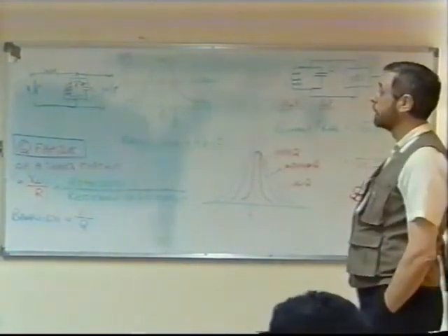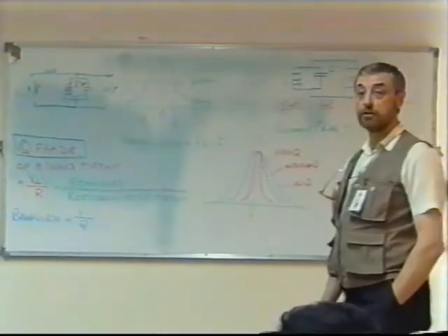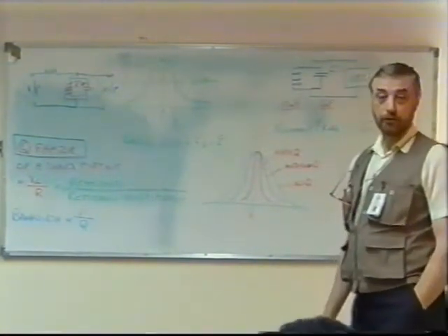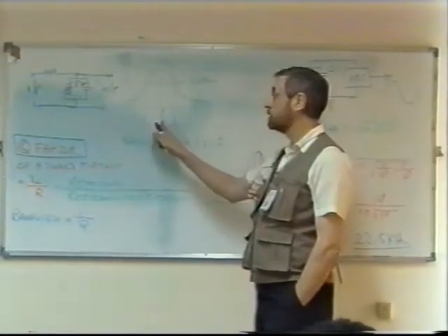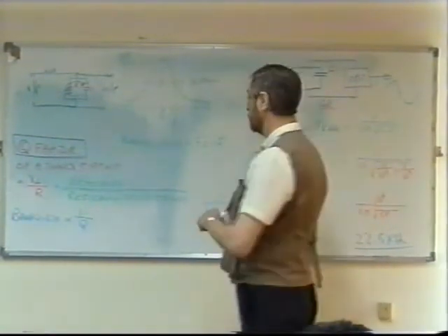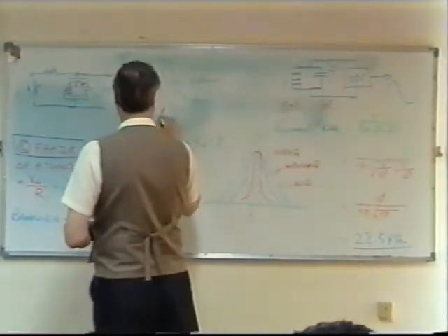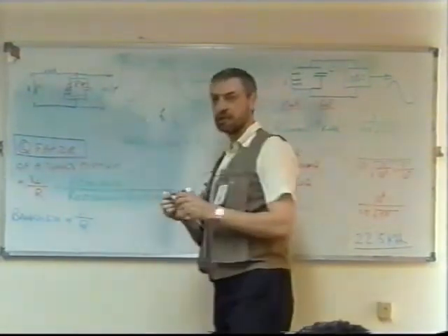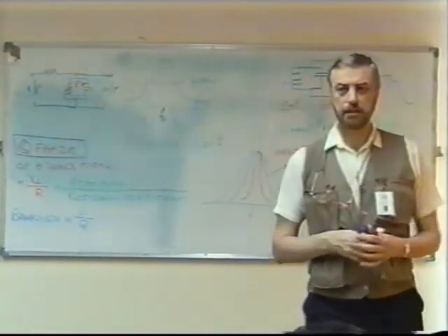But as a quick calculation, you calculate the bandwidth as F0 over Q. In other words, 1 over Q times the resonant frequency. This is F0. But I've not seen any questions like that in a test to calculate this bandwidth.